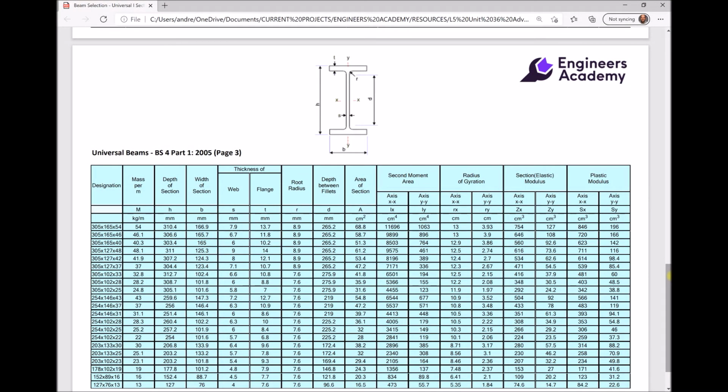In the previous video, we calculated the second moment of area for a beam based on given allowable deflection information. We had a beam that was subjected to various different loads, and we specified that that beam should only deflect by a maximum of 3 mm at the centre of the beam. Once we'd calculated our allowable second moment of area for that condition to be satisfied, we used the universal I-section beams tables shown on the screen